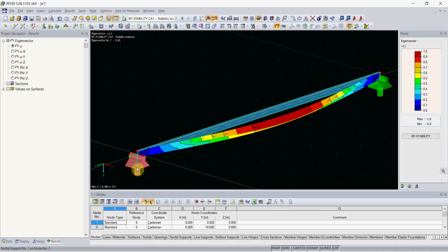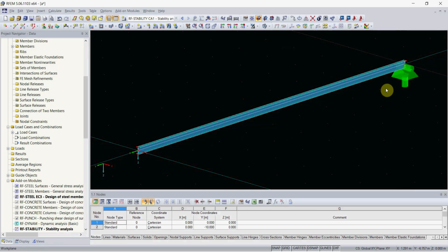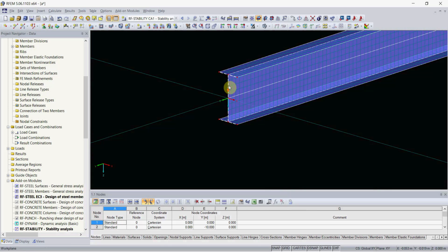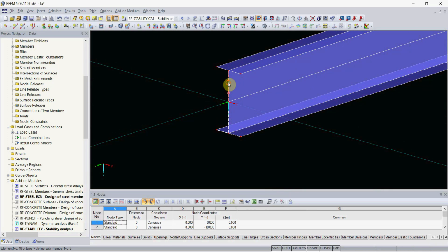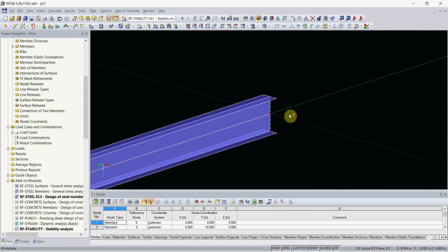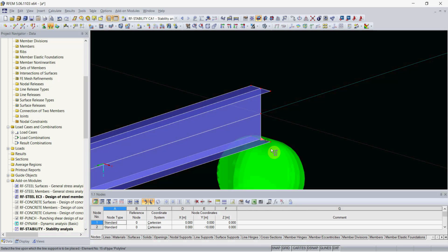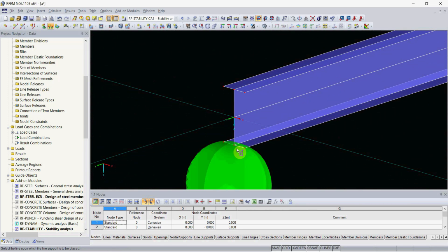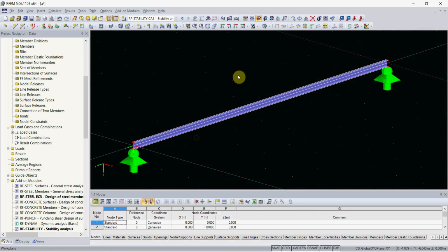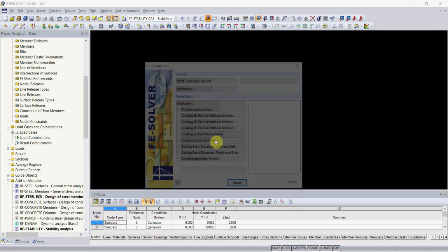And since we have the model, we can actually play with it for a bit. For instance, let's see what would happen when, instead of making a perfect hinge in the middle, we would only support the bottom flange without any sort of support on the top flange, which is a solution I often see in engineering. And sometimes designers do not take into account that such a support actually influences the critical bending moment, which in turn influences the general capacity of the beam due to bending.